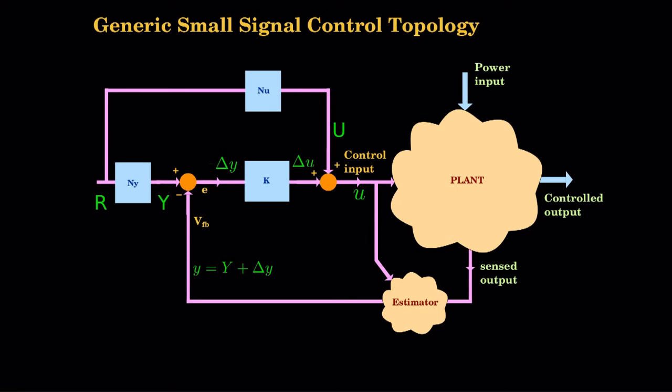You will find the error, and using the error there is a local feedback here, and that local feedback will have a gain G, and the output of that is the feedback that we are feeding back. So, this G is another component that we have to design and fix in. When you say Kalman filter, it is an optimal estimator. The Kalman filter will have some gains that we need to find out. So, that is that gain G, the Kalman estimator gain.